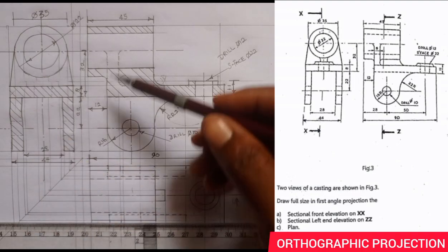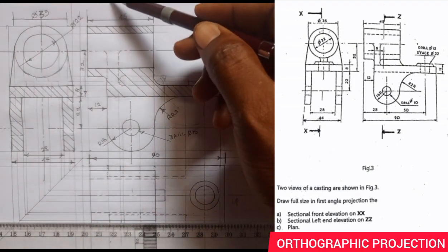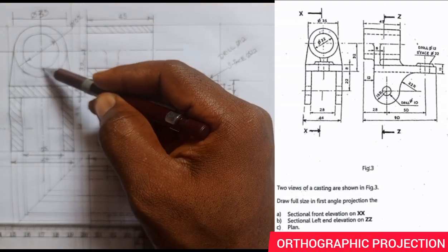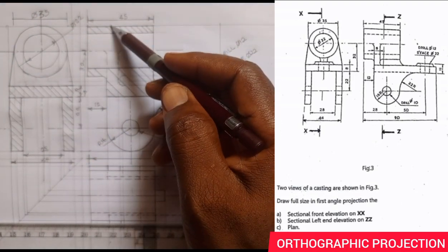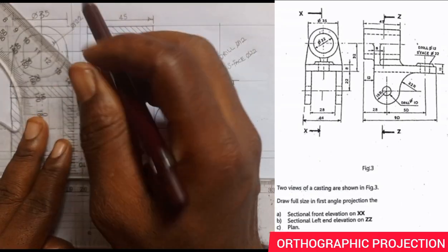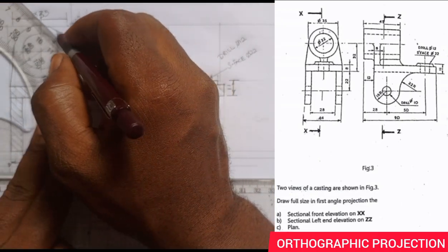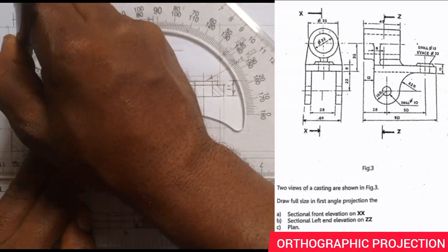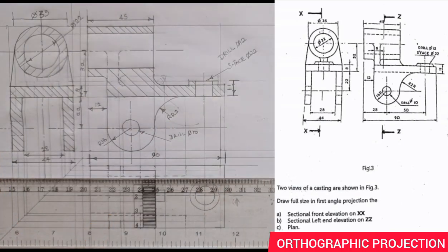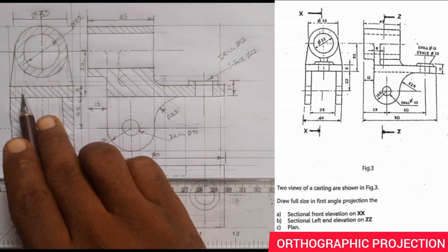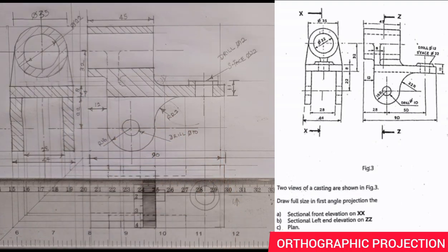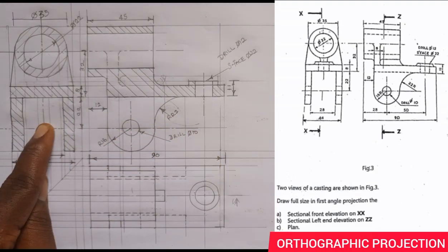Then you're cutting, right? You're cutting the plane as you can see on the right hand side this way. So you're cutting here, and you're also cutting here. It's touching the thickness of the circle. So I'm going to touch all this point here. Right? So you cannot section a web, right? So this is how it will look like once you section done.